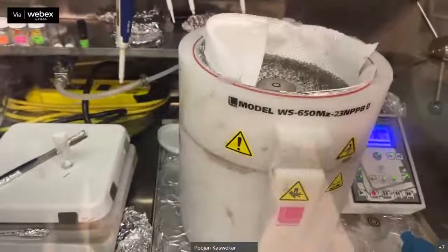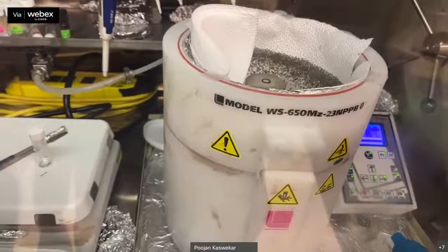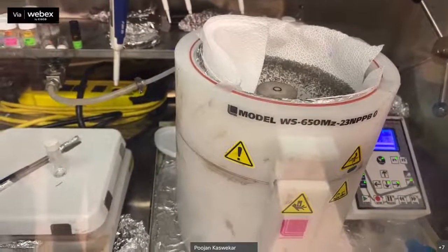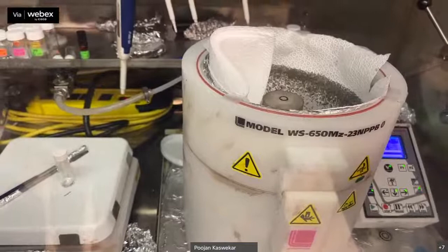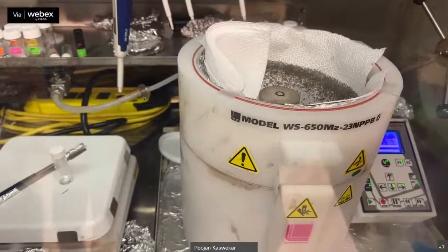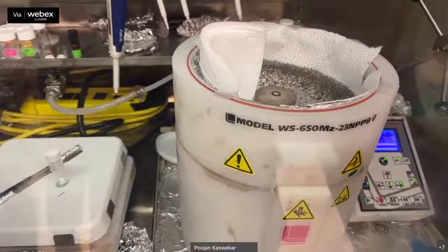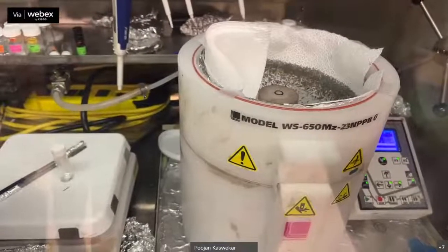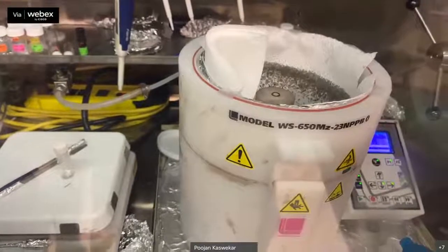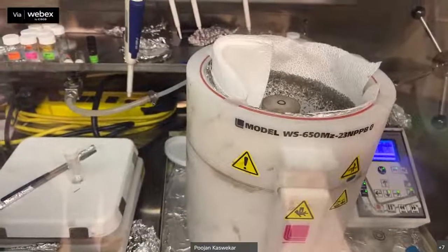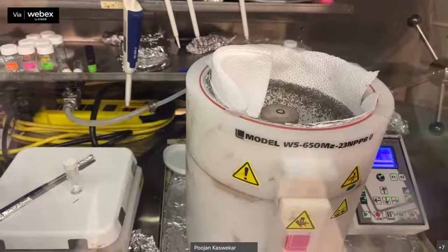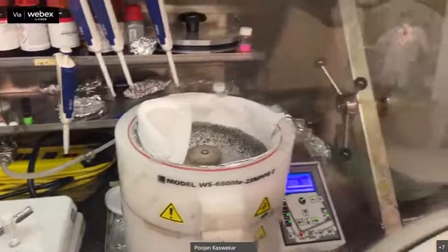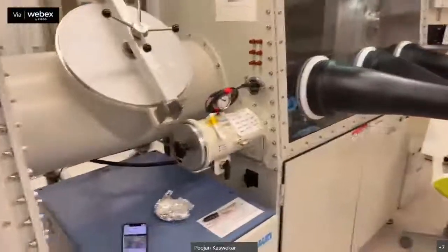And for the PEDOT:PSS layer, we are going to do it outside. So basically we are doing a PIN structure. In the PIN structure, the first layer will be the P layer, which will be outside the glove box. And the second one is the I layer, the intrinsic layer, which is perovskite, done inside the glove box. After that is the N layer, which is PCBM, basically carbon, which will be done inside the glove box. The second glove box you are seeing consists of